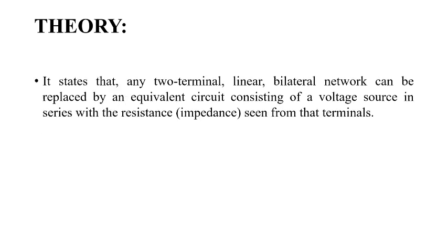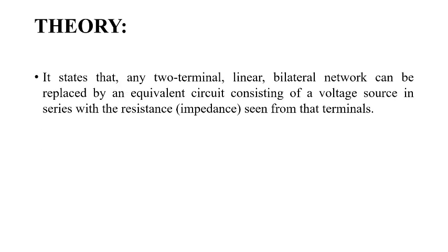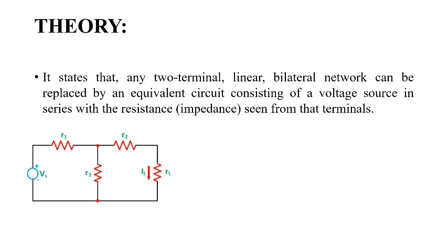So let us now quickly go through what Thevenin's theorem actually is and what it states. It states that any two-terminal linear bilateral network can be replaced by an equivalent circuit consisting of a voltage source in series with the resistance, which can be seen from those terminals. Meaning, for example, let us say we have this complex network and you are required to find out the load current IL, meaning the current flowing across this resistor.